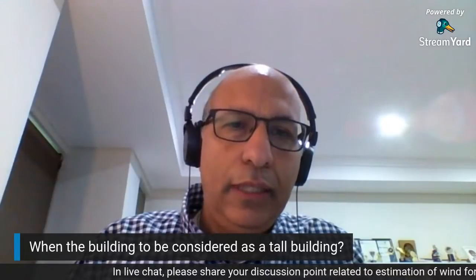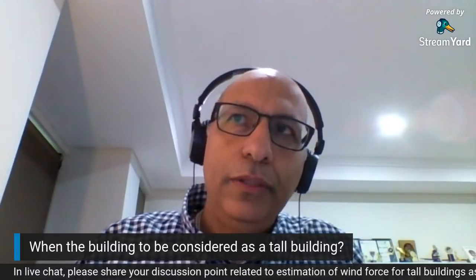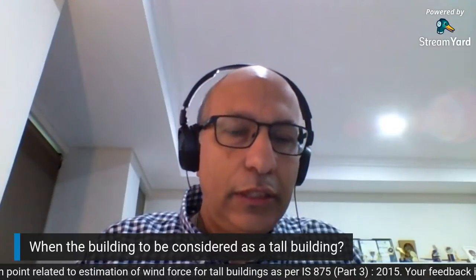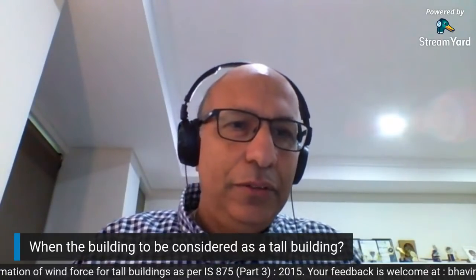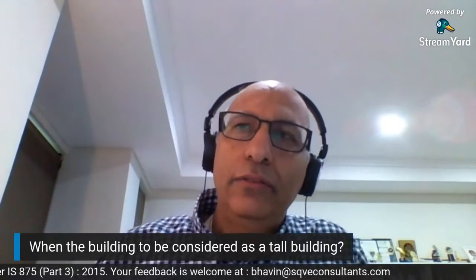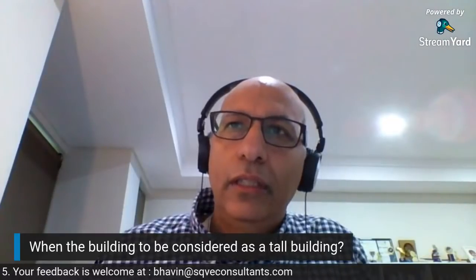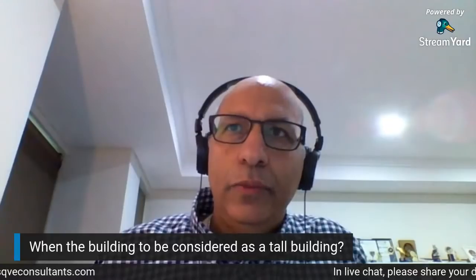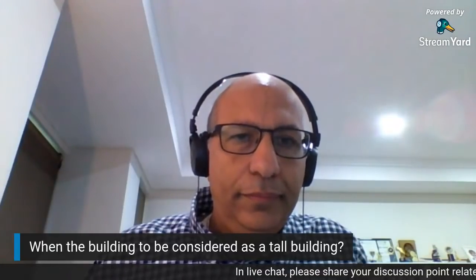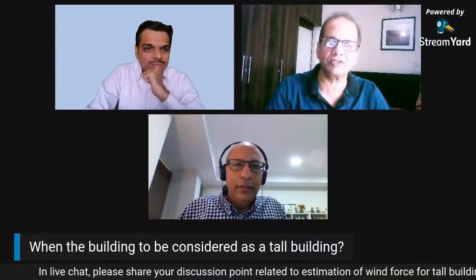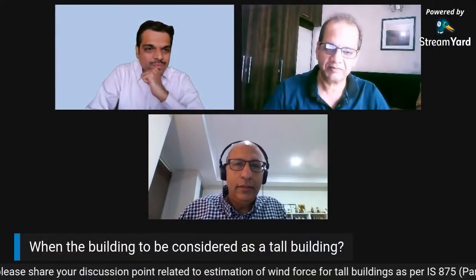There is a very simple rule of thumb that relates the height of a building to its natural frequency, and this is 46 over h, with h in meters. So when h is close to 46 meters, you get very close to 1 hertz. They're one and the same thing. I request you to explain this 46 over h a little more, because in India we are not aware of this data.